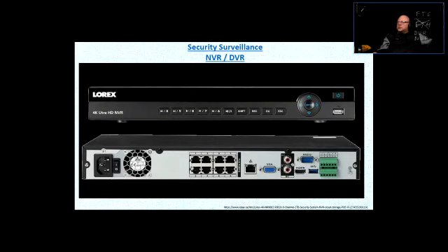Then of course you will implement something bigger than this, but you can connect this whole NVR to a network, LAN, local area network, and the cameras can be connected onto a separate switch, which usually would be a PoE-able switch.